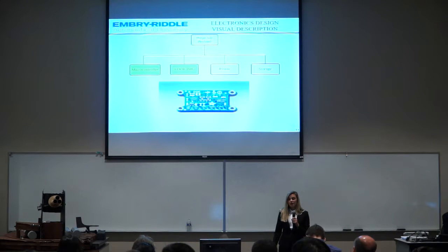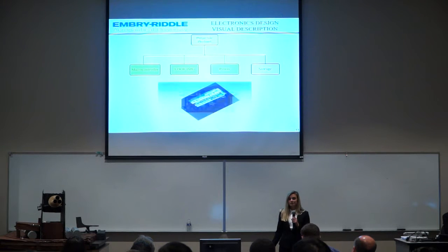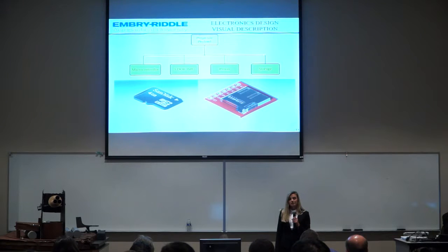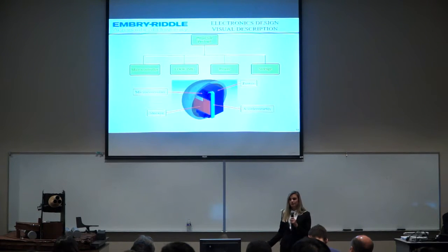The 9-degree of freedom IMU has a 3-axis magnetometer, 3-axis accelerometer, and 3-axis gyroscope, and it records the acceleration data from the flight path of the projectile. The power is responsible for giving power to all of the projectile payload elements, and the storage element is responsible for physically storing the data gathered by the 9-degree of freedom IMU. Thus completing the projectile payload, you can see them all assembled within the projectile payload to give a better idea of spacing.